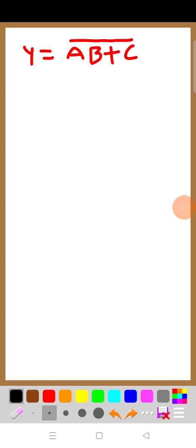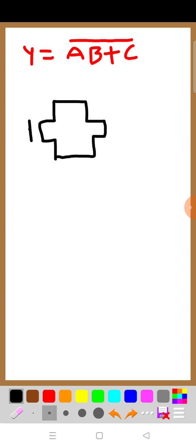Remember very carefully. Then we will see some very complex circuits. Now you can observe how to design AB plus C here. Very important point, how many inputs are there? Absolutely, 3 inputs are there. Among them 2 are in AND operation and one is in OR operation with that. Is it clear? Therefore the 2 Pmos should be connected in parallel. Let us consider these two, A and B. Now you can observe this is A and this is B.